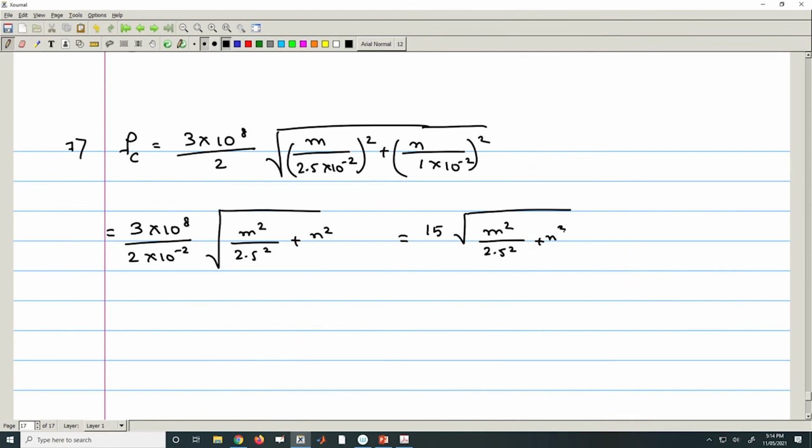Now we need to check for transmission at 11 gigahertz, find the ratio of phase velocity to medium velocity. Okay. So we'll start with FC10. We will have it as 6 gigahertz. Okay. FC20 we will have 12 gigahertz and FC01 is 15 gigahertz.